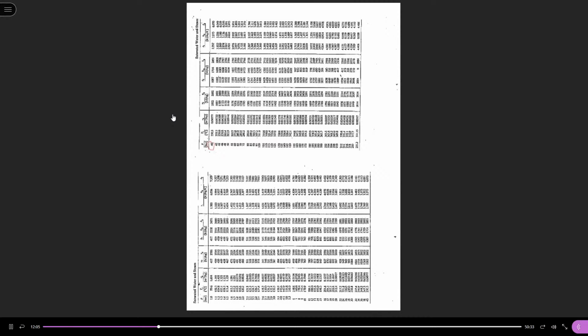Then this is the saturation temperature: 250.3 degrees Celsius. Therefore, for the given conditions, it's 500. 500 is larger than the saturation temperature, so therefore, it's superheated.